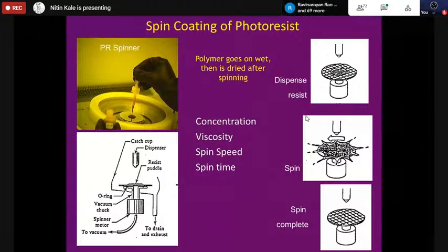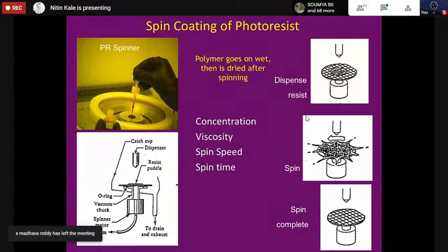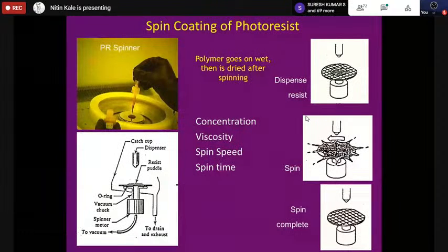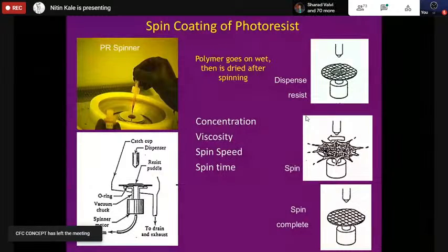At high humidity, the adhesion between the photoresist and the wafer is poor, because photoresist is a polymer and humidity is water, so there is a dislike between the two. Also, the viscosity of the photoresist depends on temperature, so temperature control of the room is important. Otherwise, you will have different photoresist thicknesses and different exposure times, for example. So things have to be in control.